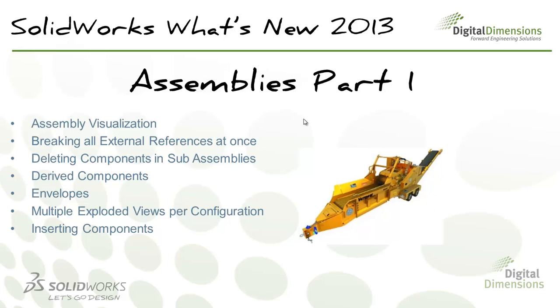First thing I want to get into is assembly visualization, some of the new features for assembly visualization in 2013, as well as new functionality for breaking all external references in one place. Deleting components and subassemblies has some changes in it that I'd like to get into, as well as some enhancements to derived components. Envelopes got an overhaul for the 2013 release, so we'll get into that, as well as support for multiple exploded views per configuration. Lastly, I'd like to get into some enhancements to the insert components command in SOLIDWORKS 2013.